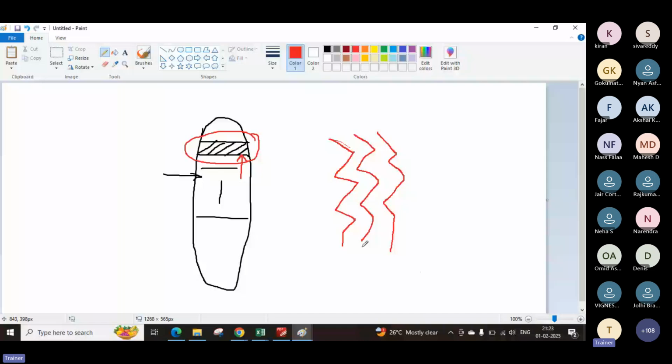These are placed in this region only. If it is vertical, your gas will come, it will strike and change its direction, and keep striking continuously while going upward. And when it strikes, as I said, it changes its direction and loses momentum. So the liquid particles will stick to the surface and form a layer, and this will trickle down and fall directly from this.